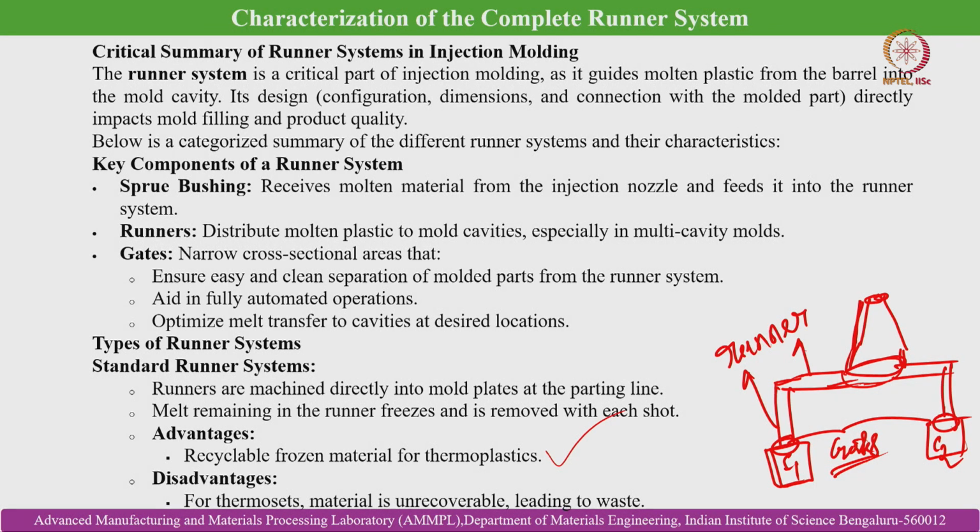You can have the luxury to design the runner, even a little over design it, in the case of thermoplastics, because you can reuse the feedstock material in the case of MIM or CIM, and plastic material in the case of polymer injection molding. However, that is not the case when you are dealing with injection molding of thermosetting polymers, because they are not reusable.